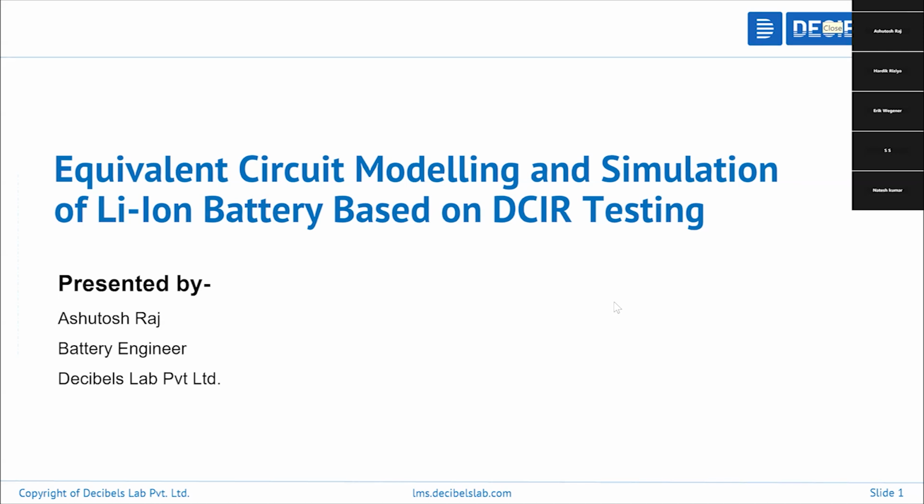So today in this bootcamp, we will deal with the modeling of the battery, especially equivalent circuit modeling, and how to get the model parameters from a test. Especially we will deal with the DCIR test. Then we will go forward with validation and the simulations in MATLAB and Simulink.